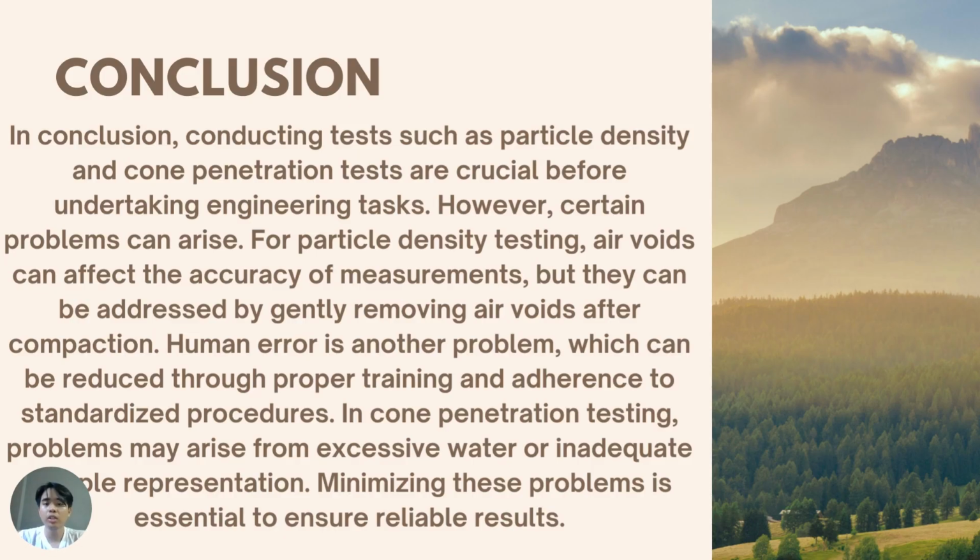Conclusion. In conclusion, conducting tests such as particle density and penetration tests is crucial before undertaking engineering tasks. However, certain problems can arise. For particle density testing, air voids can affect the accuracy of measurement, but they can be addressed by gently removing air voids after compaction. Human error is another problem which can be reduced through proper training and adherence to standardized procedures. In penetration testing, problems may arise from excessive water or inadequate sample representation. Minimizing these problems is essential to ensure reliable results.